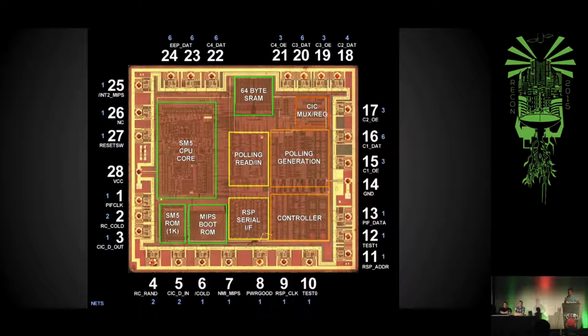So if you look at the top right corner, you'll see 666, 36364, and those are a lot higher than the ones on the bottom left. So I'm thinking that these pins have alternate functionality, just like the CIC, and that you can use them for arbitrary code execution. Now, this is future work. We just discovered this like a week ago. But we're really hoping we could run our own code on this chip. This has its own 1K ROM as well, but it's actually fully utilized, unlike the CIC that is basically half empty.